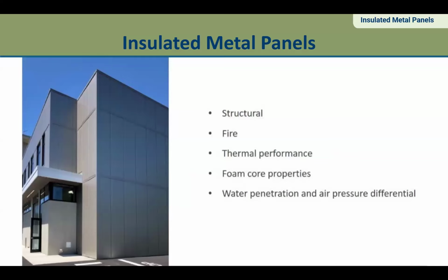Insulated metal panels are structural in nature, so you can space your framing out further apart. There's no universal truth. It depends on a variety of factors, but we'll say 6 feet is a pretty standard and safe span length for these panels. As I mentioned, they do meet NFPA 285 fire code, and with the mineral wool core, which is available, you can meet those 2-hour, 3-hour walls as well.